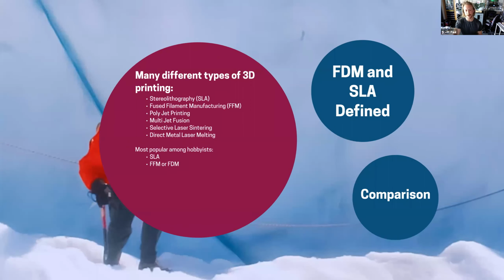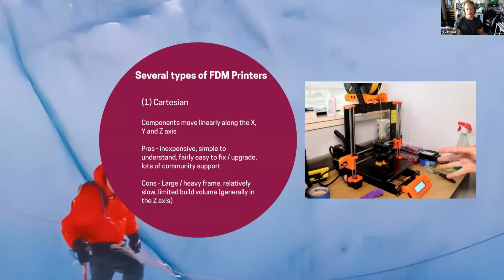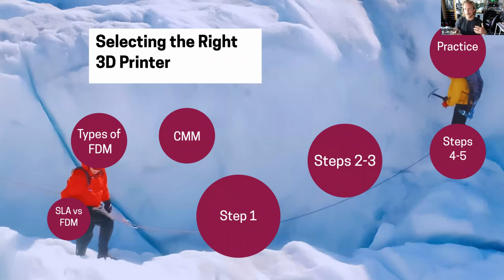Both are great and can be used for a wide variety of things. Like I said, we have an FDM printer at Luxel, and we use it on a weekly basis, if not daily sometimes. So FDM certainly has its place. It's cheaper. It's fairly plug and play, and it's a great form of 3D printing. Because I would consider SLA to be more involved, and also a bit more expensive, for the sake of going through this selection process, I wanted to focus on just FDM.